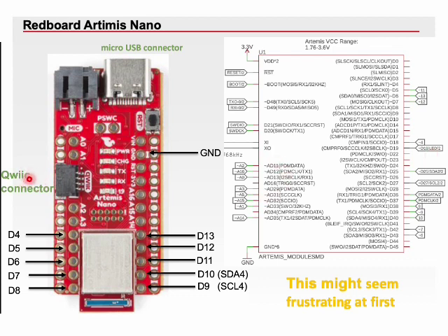The I2C pins on the Sparkfun Redboard Artemis Nano are located on the board's edge at different places. Specifically, you can see the ones I labeled as SDA4 and SCL4 on the board, and are located at D9 and D10 pins.